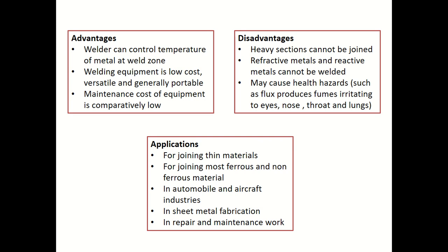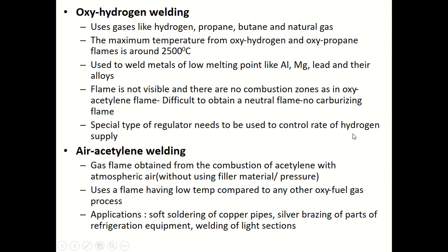What are the applications? It is used for joining thin materials, and joining most ferrous and non-ferrous materials. It is widely used in the automobile and aircraft industry. In sheet metal fabrication work, this type of welding is used. In repair and maintenance work, gas welding is used. And let's become familiar with a few important techniques in gas welding.